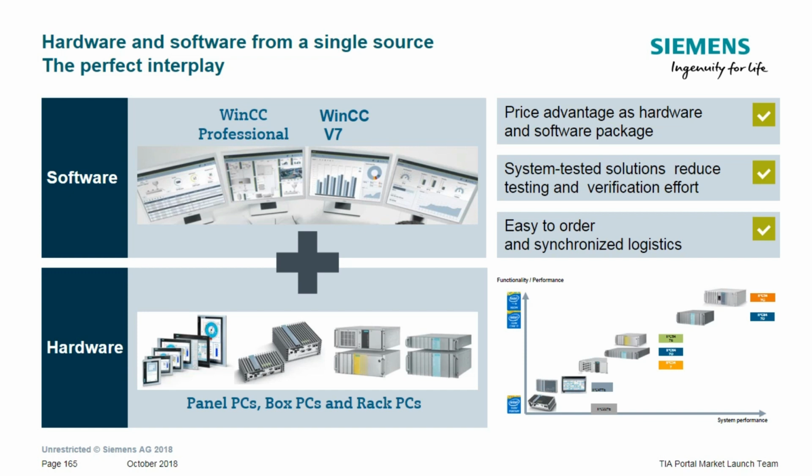In that case, we want to install version 15. And then we find here our added software. We can also configure the software. And then we can just say, I want PC-based HMI SCADA. I want an engineering and a runtime system. I don't have an existing WinCC software. If I would have, it would give me all the information regarding operating. Engineering software, I want to have TIA. Okay. I'm just going to go to the package.